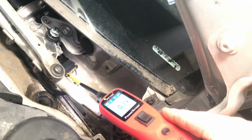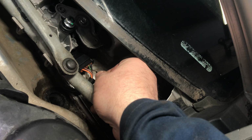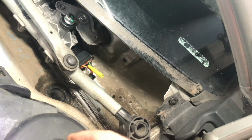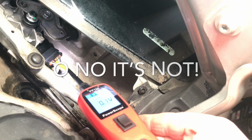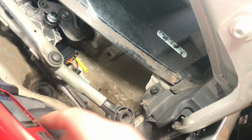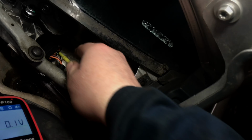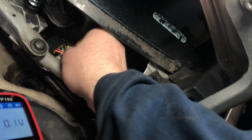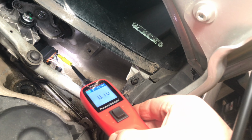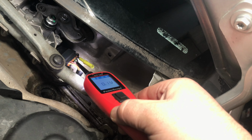So nothing like that. Then that's showing a ground, but I think this is the real ground here. Brown is ground. And then one of these pins here, that would be a power. I showed 12 volts. I think that's for the slow speed, the green. And then the other one will be, well, not really sure what that is. So we've got ground, ground, power and ground.